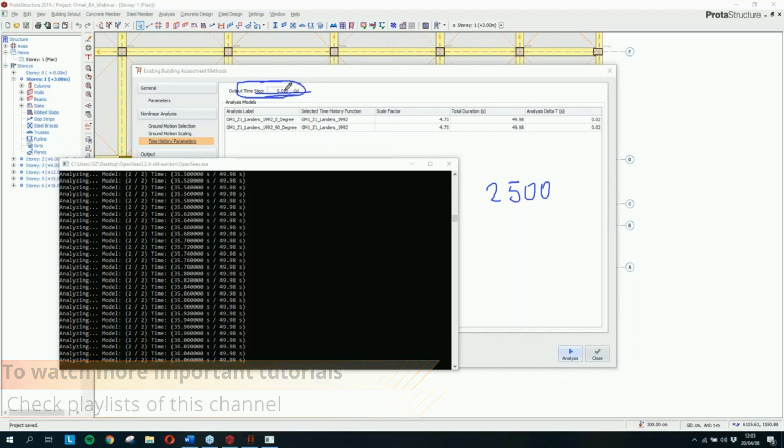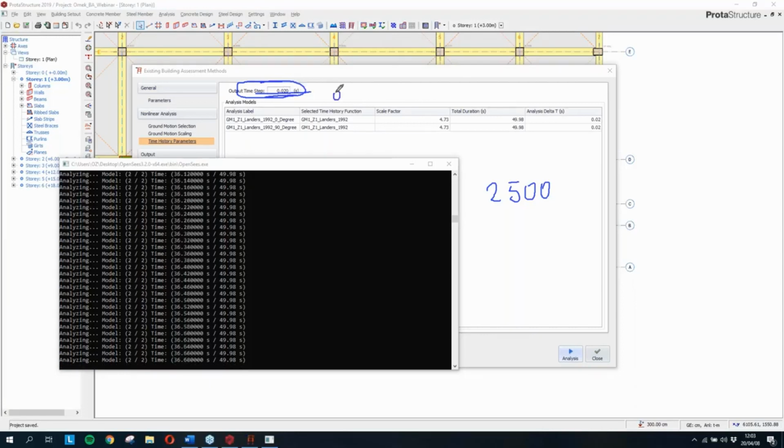If you change this value from 0.02 to 0.04, the results are recorded by skipping for those selected intervals, and for each member, for each end, I end and J end, for these time steps, all member dynamic responses are created in the model directory.